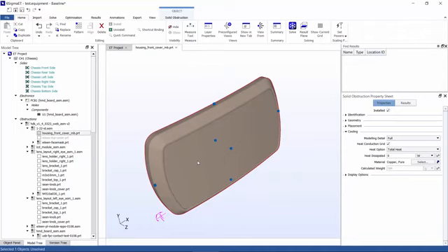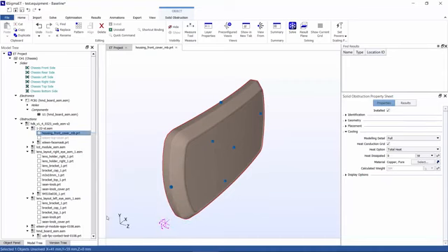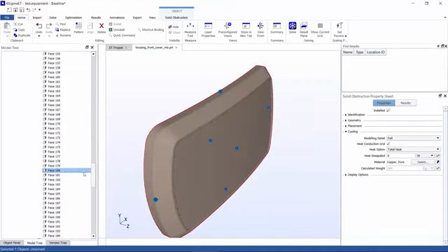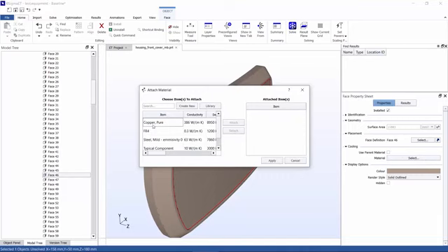calculations. So what we can do is right-click on the object, and we can add all faces. And this breaks the object surfaces into individual face objects, allowing you to provide different properties from the parent object. A good example would be applying a surface with a different emissivity value than the parent object. I can go in and select a different material with a different emissivity.